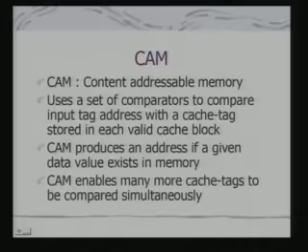The basic idea is that I take the tag, just consider it this way. The moment I take the tag, if I can use the tag to get the address which is really stored in the cache, and I use the tag to generate that address in the cache, I have effectively done almost a fully associative memory.